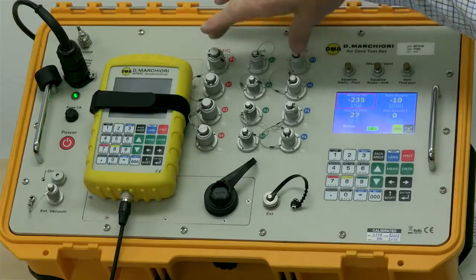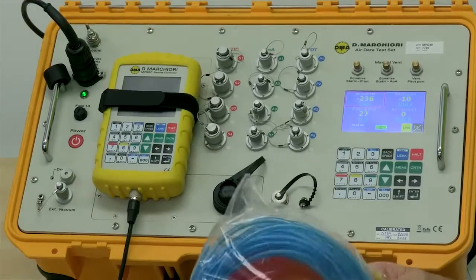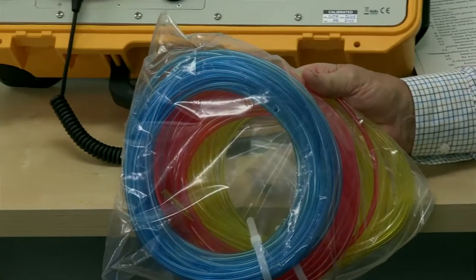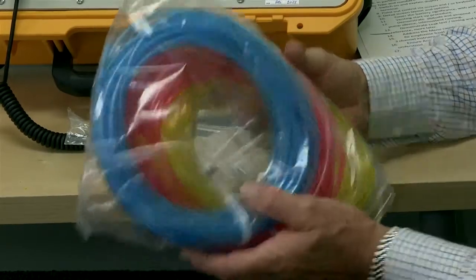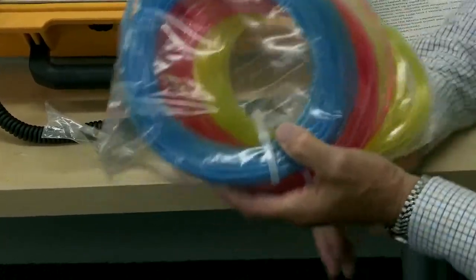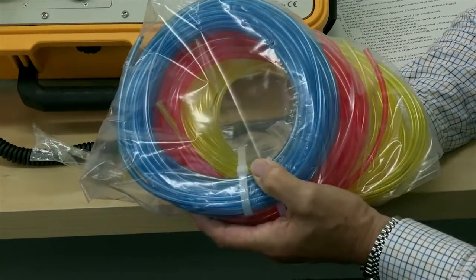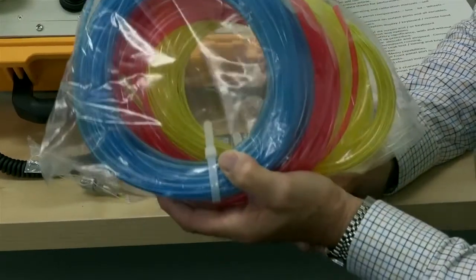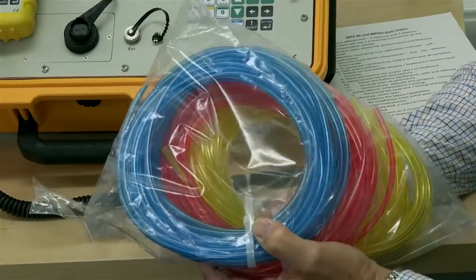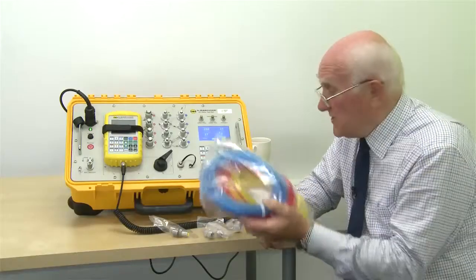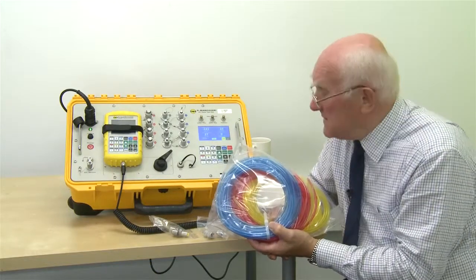And from the point of view of how we get to the aircraft, we supply you with hoses which connect through to the aircraft adapters. We tend to use transparent pipes which are colour-coded so that they line up with the connections on the instrument. You can use different hoses if you wish. We tend to prefer the lightweight, coloured, transparent so you can see any rubbish which has got inside the system and make sure it doesn't get into the test set, although they do have filters to protect against really big problems.